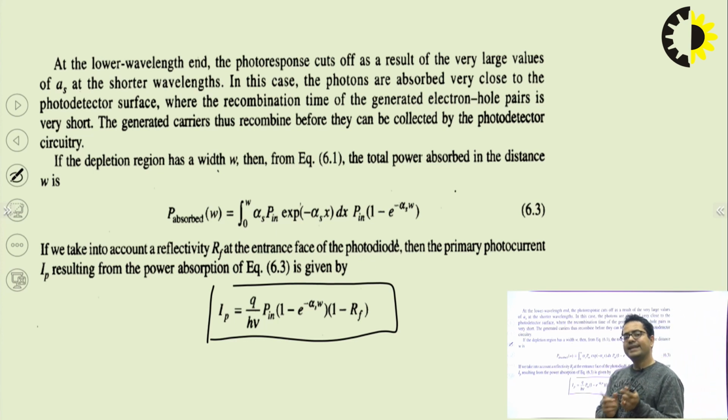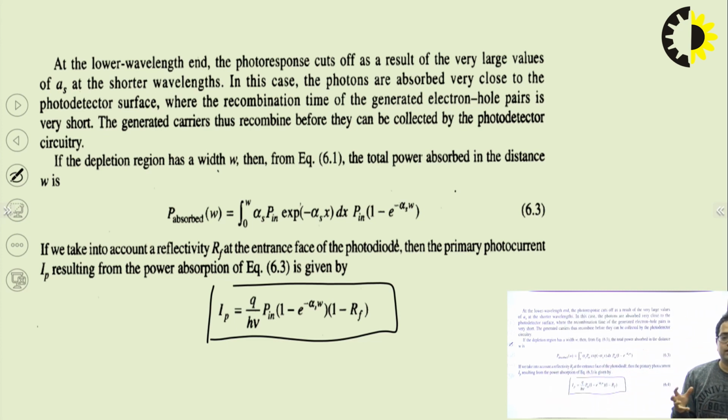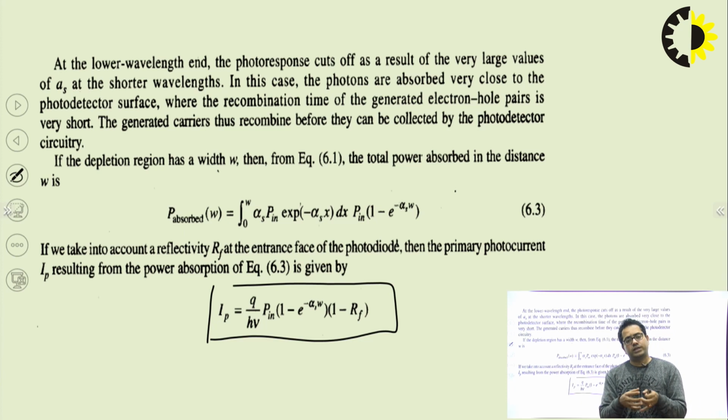Now that leads to the idea of a pin photodetector, in which there are two materials, p type and n type, and between these two we have created a high-width intrinsic layer, so that the depletion width is increased because of the reverse bias. As we have intentionally increased the width of the intrinsic layer, more photons will be incident and free the electrons, generating more electron-hole pairs, right? So with this we have somehow increased the performance.